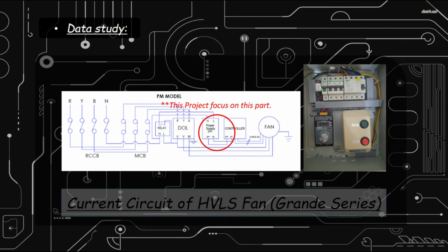One wire goes to the AC-DC converter to supply the controller circuit, and then the control circuit connects to the BLDC motor using a 4-core signal wire. So this is the idea to change the analog controller to a remote control system.